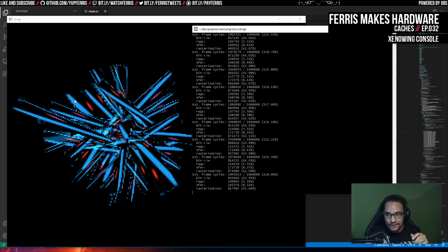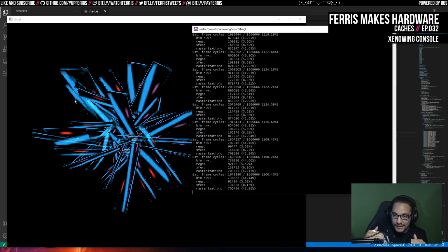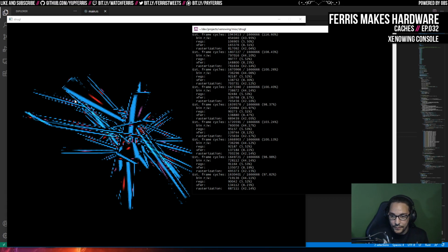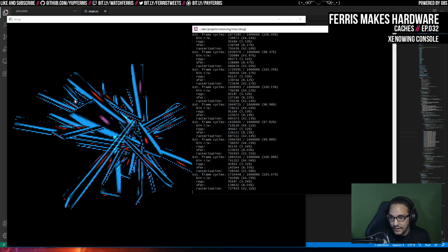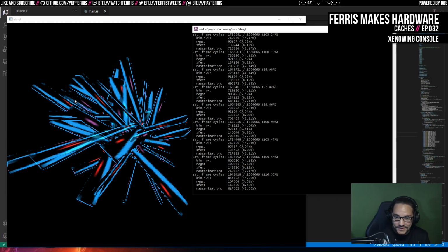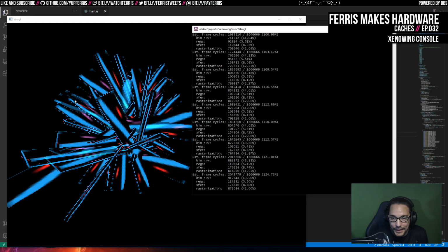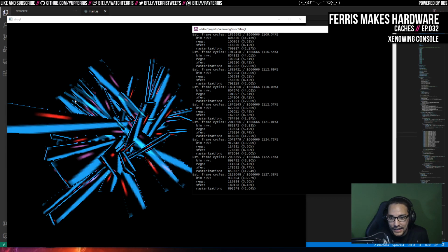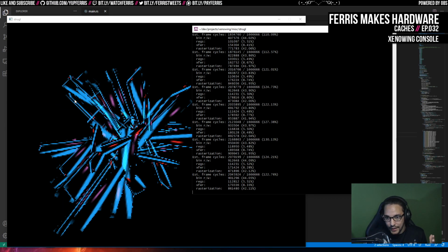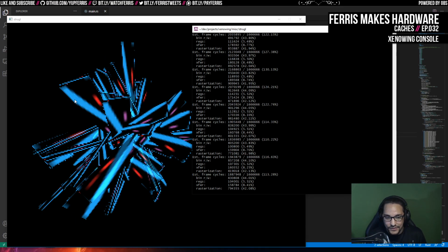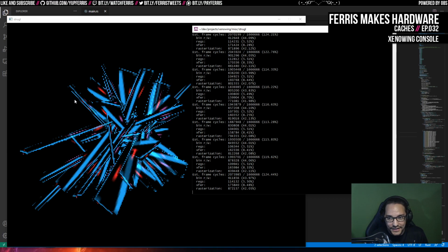But if I'm going to use that mechanism to get 4 per cycle to feed 4 pixel pipes, then I need to also double the memories. I'll have to use some duplication there, which in terms of bandwidth is fine because I'll just write to both memories when I read that data in. But in terms of capacity it's potentially problematic. Right now, the max texture size is 128 by 128, which was decided because I was shipping textures all the time, and that was going to be like 64K worth of memory just for that texture cache.